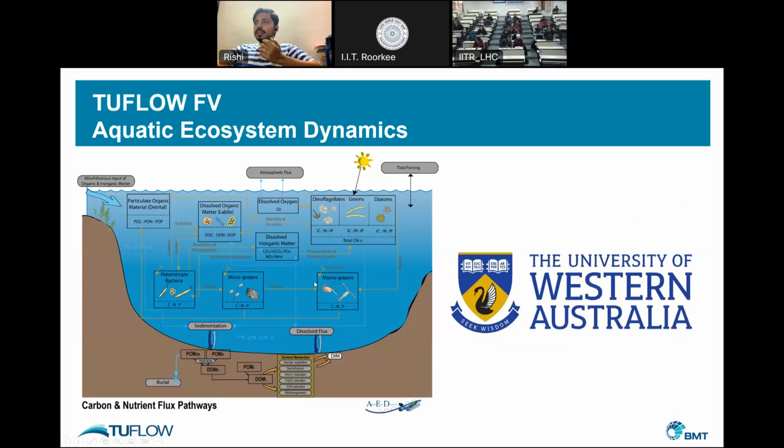TUFLOW FV is now integrated with the AED software for modeling all the water quality parameters: dissolved oxygen, nitrogen and phosphorus cycles, and you can do pathogens as well as phytoplankton and zooplankton. Almost all the water quality parameters can be simulated with TUFLOW FV.